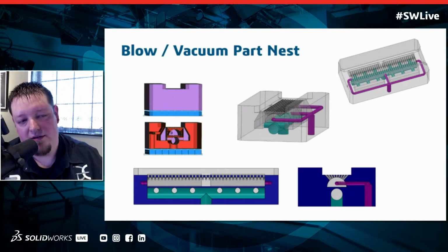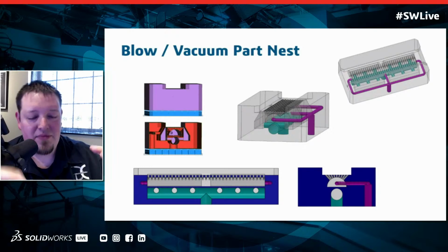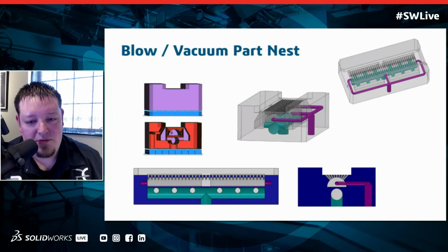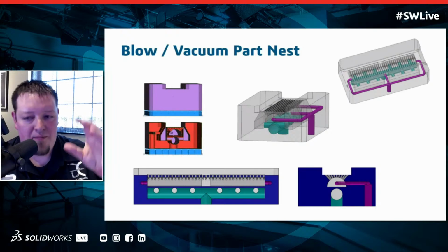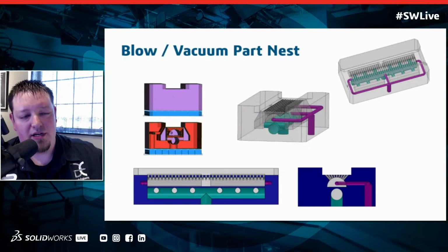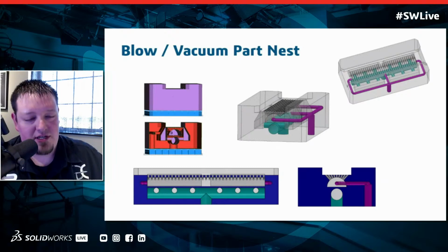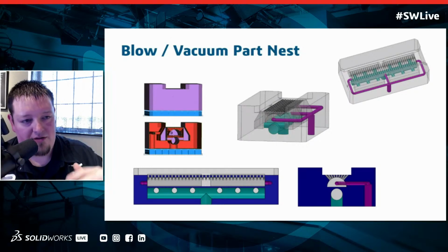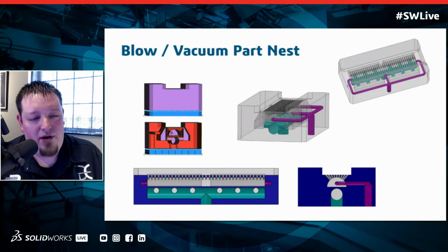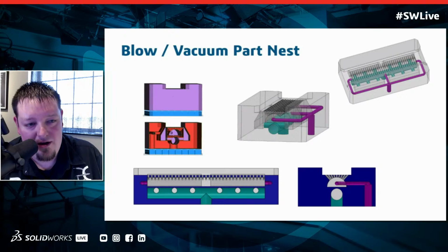And then the vacuum vaults on either side have that 60-degree angle. Anything over 45 degrees is a self-supporting structure. So you don't have to have supports printed inside of there. And because this is a single piece, you couldn't ever get the supports back out from inside of there once you printed it. So it's very important in a situation like this, not only to have self-supporting geometry, but also, since we're printing in a liquid resin, you can drain the resin back out again, flood it with isopropyl alcohol, shake it real good, wash out those interior chambers, and you're left with a perfectly functional part that you can blow air through, you can vacuum materials through it, and you don't have any support structure left on the inside for everything to get hung up on.